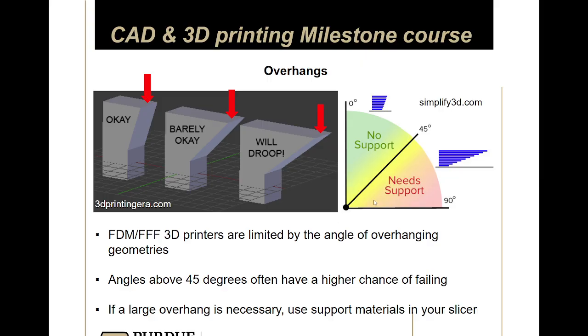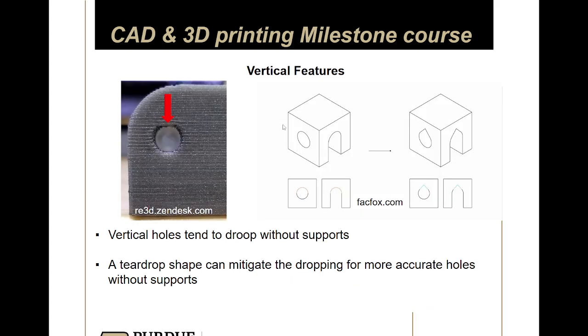So you'll see that if a 3D printed part was designed well, a lot of people will just put a bunch of chamfers everywhere. One thing to note is chamfers versus fillets. You know how to use both tools, right? In the 3D model, the fillet is rounded, but the chamfer is flat, right? Depending on which orientation your print is at, the fillet may be a bad option, right? Because if you think about the circle, I guess it's good to see on the next slide.